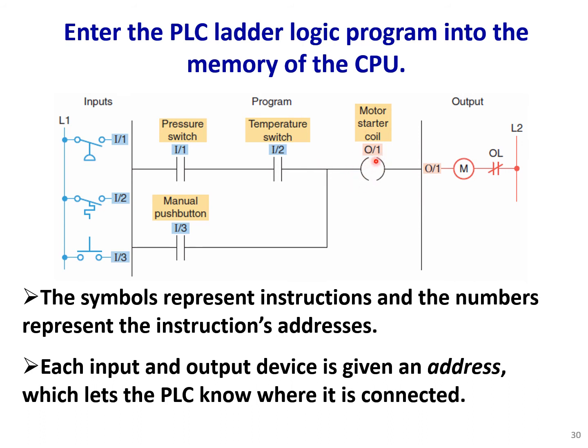And since the starter coil is connected to the first port of the output module, or O1, the coil also should have the same address.